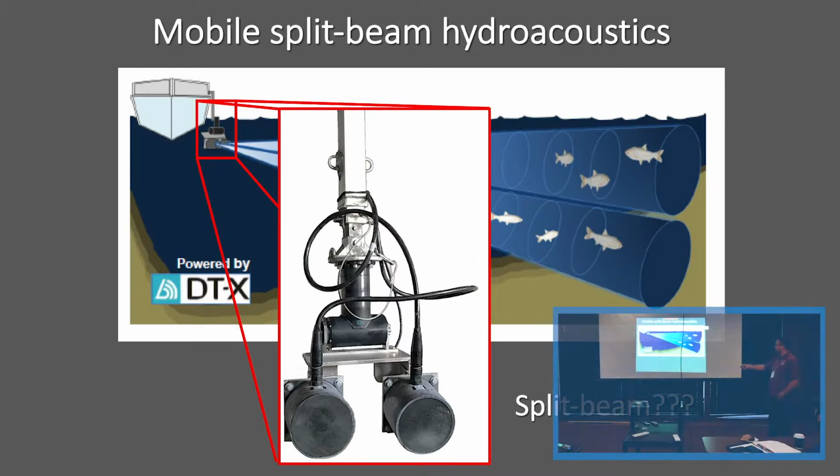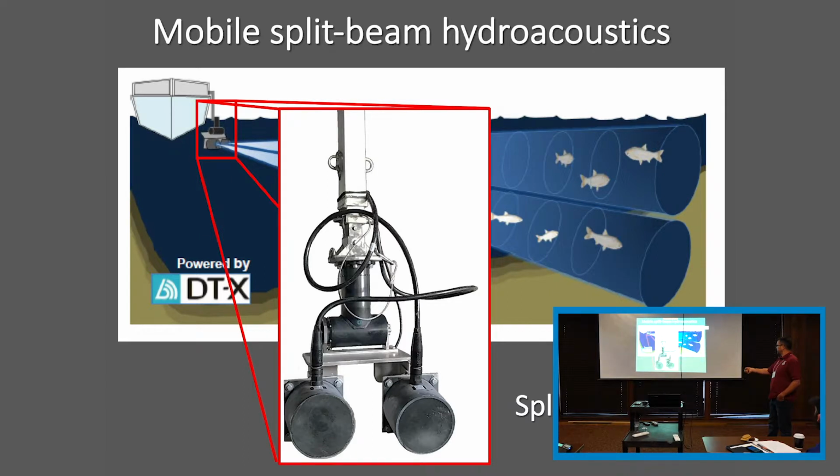So what we have is a rotator that can adjust the beam left and right, up and down. We use that to control our angles so that we can have one beam running parallel to the surface and another beam that's pointed down. So we're maximizing or increasing the volume of water that we can sample. And each one of those beams is emitted from 2 separate transducers.